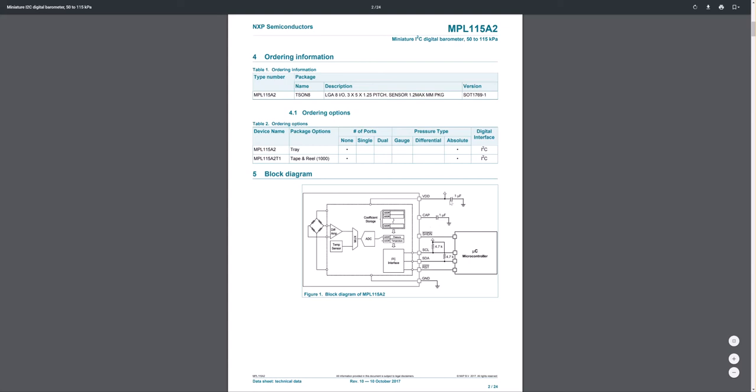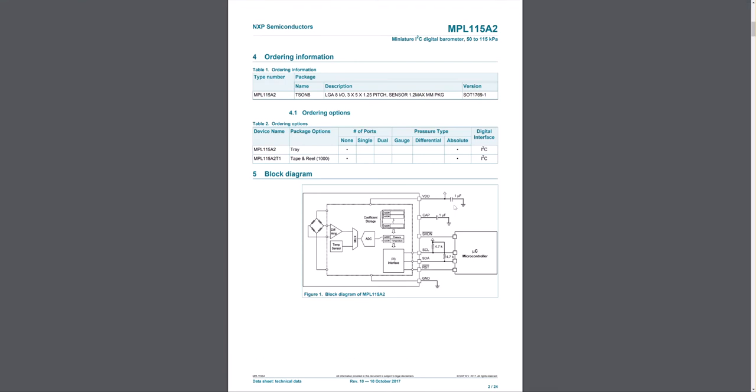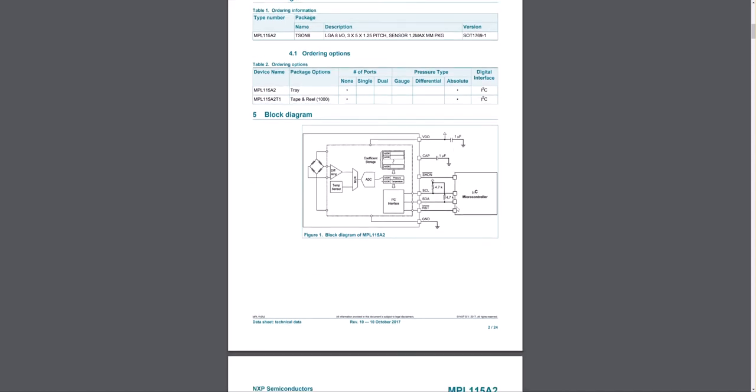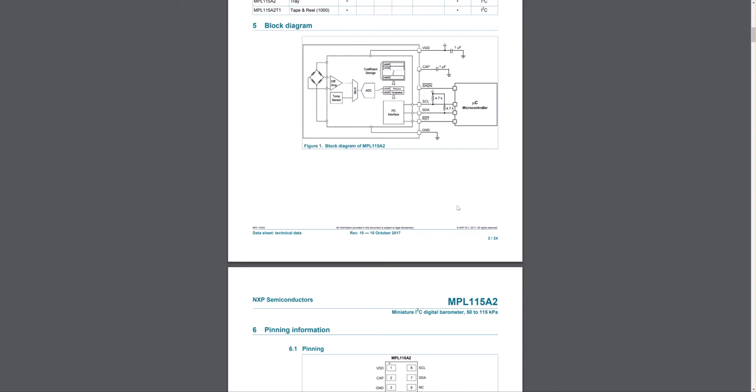This capacitor here though is more for a power cap. You'll often notice that you'll put like a 1 microfarad in parallel with the power supply, or even a 0.1 microfarad. Lots of chips or ICs require that, and that's just to make sure that any kind of power demands that the chip might have, it can meet those power demands, meaning if it needs a lot of charge at a particular moment in time, this capacitor will be charged up and it can just pull it from this capacitor.